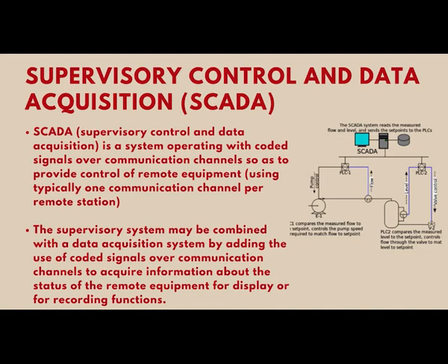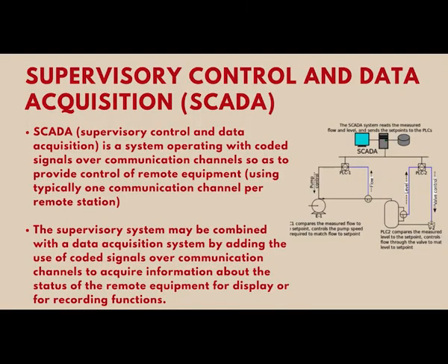So earlier, there used to be a clear difference between a SCADA system and a distributed control system. SCADA systems were generally used for small plants or a specific area where repetitive actions are happening, for example, a gantry operating system or an LPG bottling plant, while the distributed control system is primarily used for large chemical complexes like a refinery or a fertilizer plant. But today, there is little difference between a SCADA system and a DCS. Most of the SCADA manufacturers have got into DCS, and most of the DCS manufacturers have got into the field of SCADA. There is not much variation between them, and most of the features are available for both systems.